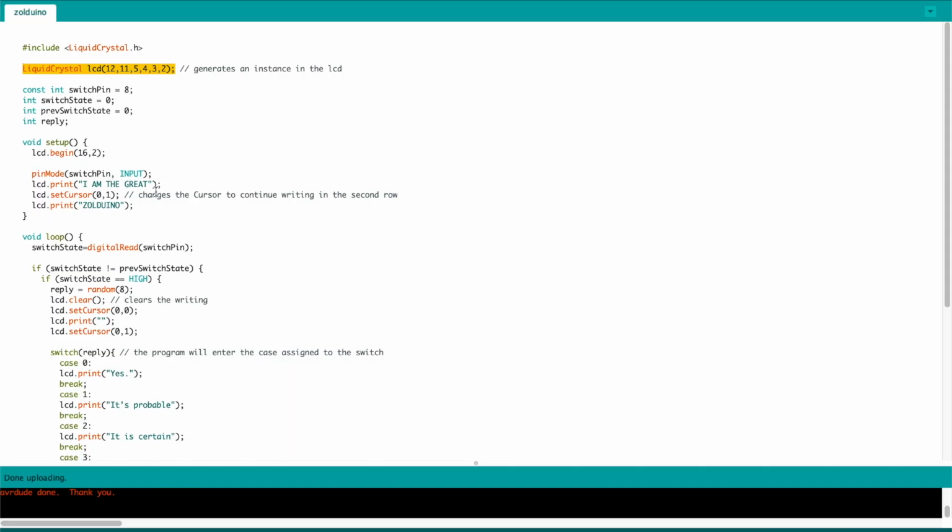The LiquidCrystal function creates a variable of the type LiquidCrystal. The display can be controlled using 4 or 8 data lines. If it's the former, omit the pin numbers for D0 to D3 and leave those lines unconnected. The RW pin can be tied to ground instead of connected to a pin on the Arduino as well. And if so, you need to omit that from the function's parameters.